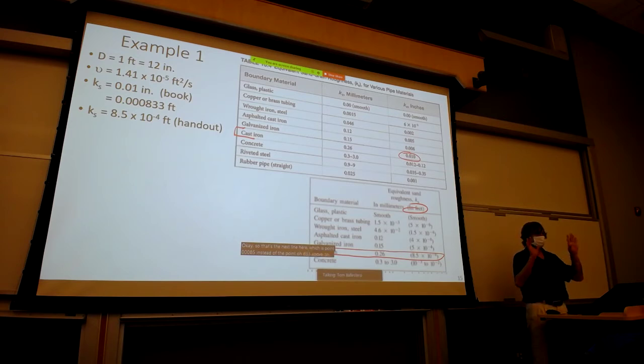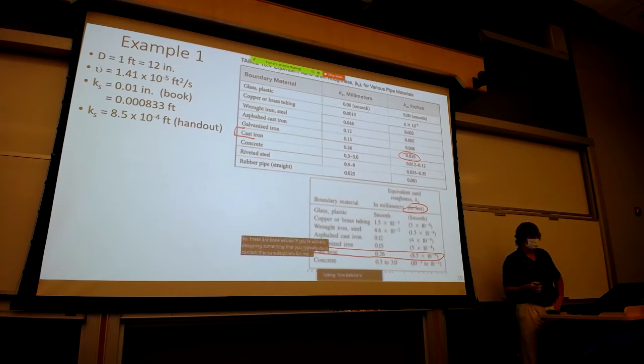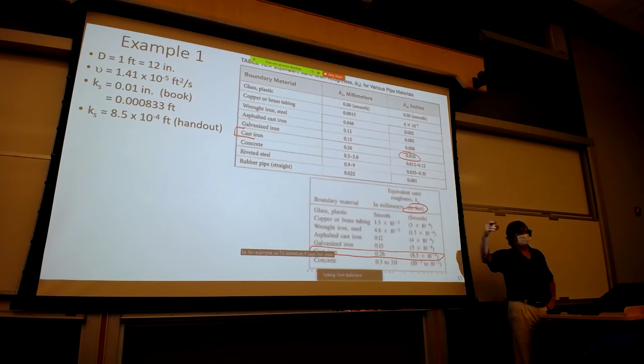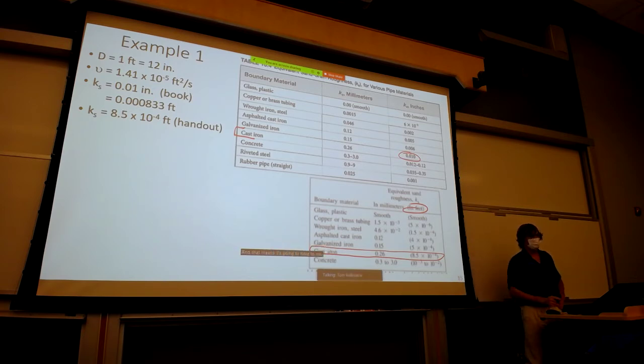So these are book values. If you're actually designing something, what you typically do is contact the manufacturers who are making this product, and they will give you this information. That's the best source. When you're writing specifications for bid documents, you can identify the pipe from a specific manufacturer, and then you always say, or equivalent. So for example, ASTM Schedule F cast iron pipe from so-and-so, or equivalent. And that means it's going to have to meet this kind of performance specification.